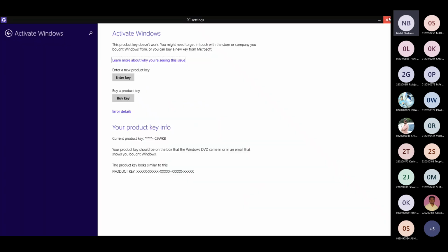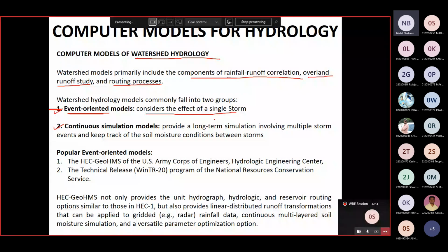Continuous rainfall event is where we can study with respect to a longer time span. So it is called a long term simulation process. Say if you are going to study the last 40, 50 years of data, you have to carry out the study for those 40, 50 years, so that will be considered a long term simulation. Again, you can also consider 1 year, consisting of 365 days. Out of that, for some number of days there is rainfall, so you can consider the monsoon time span. That monsoon time span will again be considered a long term period.